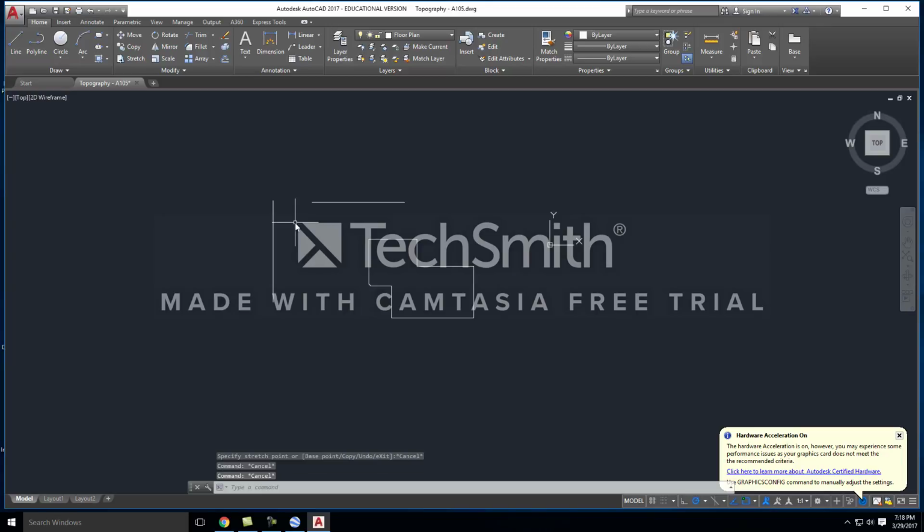So understanding how these tools work, the first thing you would do is go to fillet. Now I'm going to click on radius one more time because I have a 15-foot radius currently set, but I'm going to change the radius to 0, and then I will select my first line and my second line, and that will join those two lines together. So that's probably fillet. Between fillet, line, and polyline, those are probably the most common line tools that you'll use. You'll use them absolutely all the time.